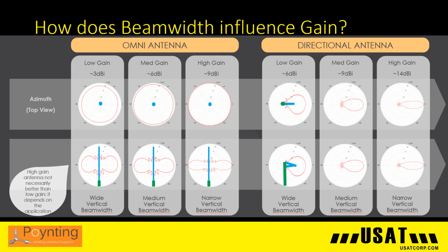Now looking at the side view of those same antennas, you'll see how the gain increase happens and what you're giving up in exchange for the gain. The side view of the radiation pattern shows a marked difference in the antennas with different gain specs. In order to get the highest gain from an Omni, the radiation pattern is focused narrowly in the horizontal direction. Not so good if you're in a valley or a hill, but great if the terrain is somewhat flat.